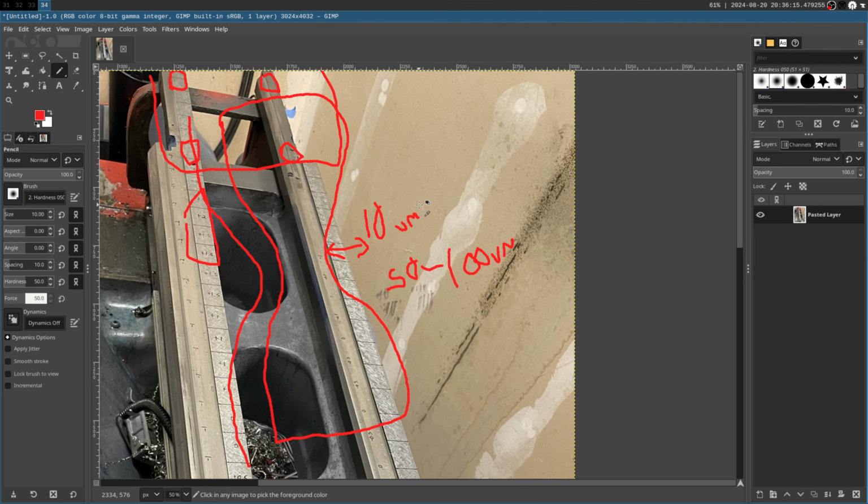But what I'm trying to do is make everything flat, square, and parallel in the same plane, such that in the future, I don't have to think about, oh, was this supposed to be a little bit lower? Was there a dip here? Should I restore the dip because the headstock expects that? From my viewpoint, when 30 years from now someone tears down this machine and is trying to figure out what needs to be repaired or fixed, if they lay a straight edge across it, it's pretty apparent that the whole thing was made flat, in which case restoring the whole thing to being flat is the correct thing to do.